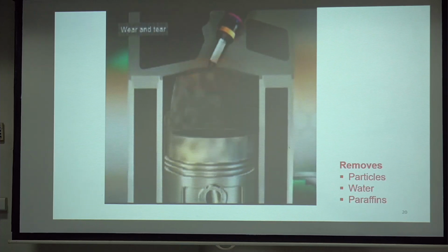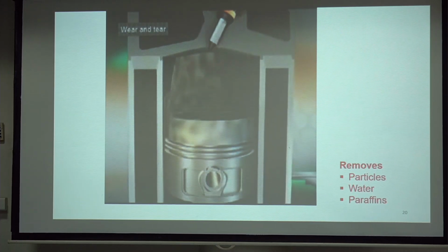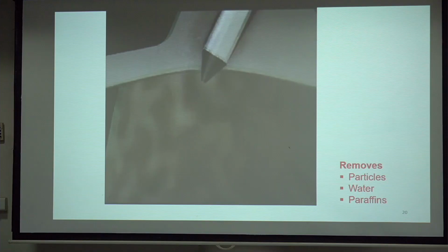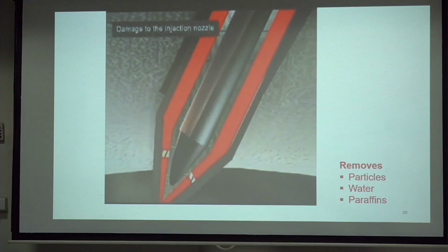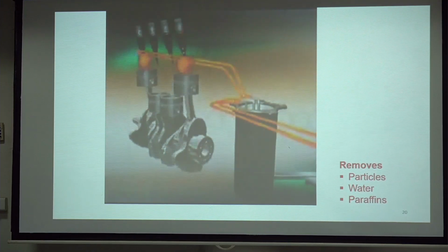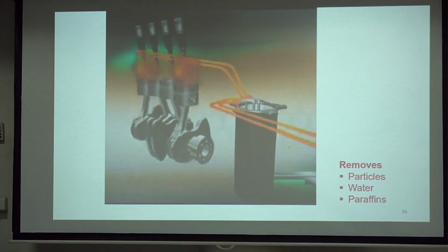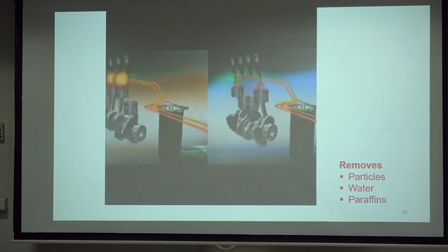Scoring of the injection nozzle and wear of those engine parts lubricated by the fuel can be expected if the filter medium is damaged. This has a serious effect on the injection process, and the engine output drops.